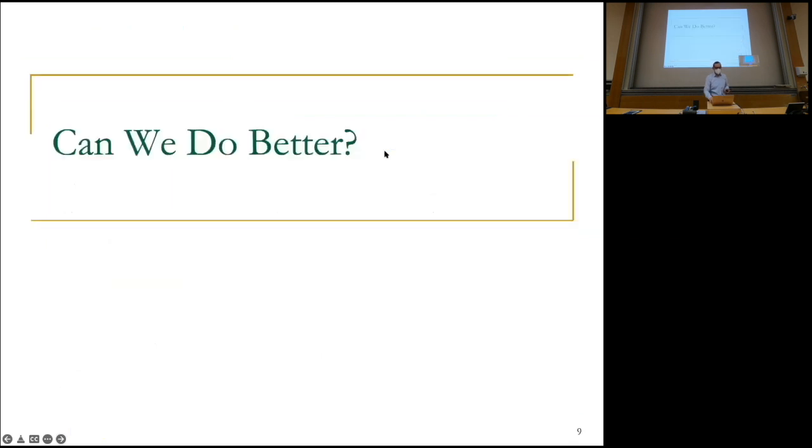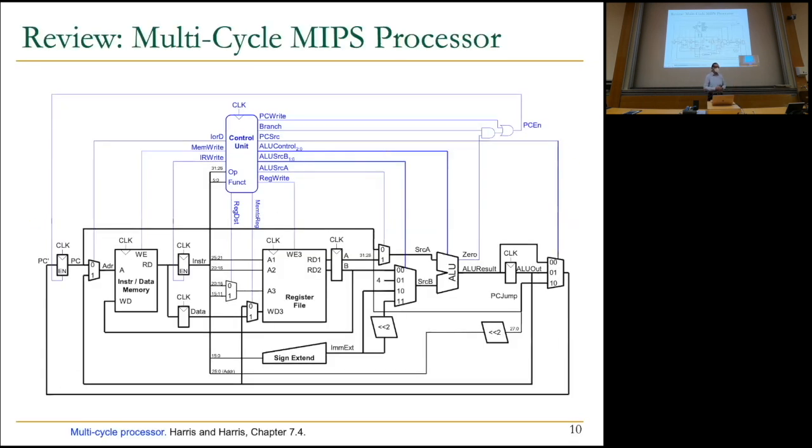So we built the multi-cycle MIPS processor that looks like this, essentially. Which essentially says that an instruction can take multiple clock cycles to execute. And those multiple clock cycles are whatever is needed for a given instruction. An instruction can take 1,000 clock cycles. Another instruction can take 1 clock cycle, if possible, or 3 clock cycles. Now you actually have a lot more freedom to optimize the performance of this machine. So we thought it was beautiful, as we discussed.